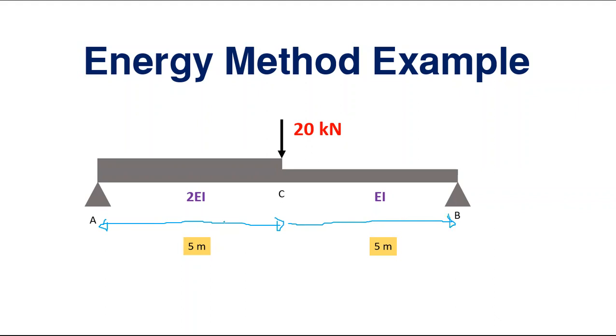And then it's becoming EI. So the material would be the same. So probably the I value, not the area, is two times. I value is two times, right? So don't get it wrong if I and 2I are there. It doesn't mean that if this area is A, then this area should be 2A. It is wrong fundamentally, right?